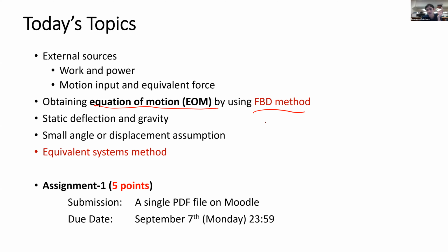That works for simple problems where we draw free body diagrams of few components, but for a complicated system we need to draw multiple components, draw the free body diagram of each component, obtain several equations, and solve them to obtain the final equation of motion of a single DOF system.